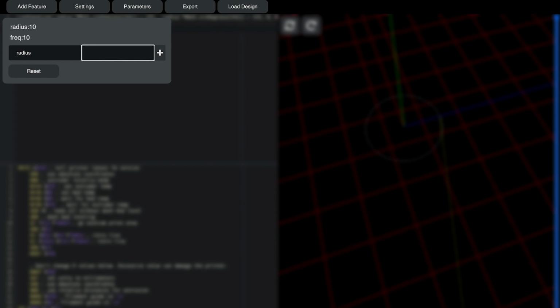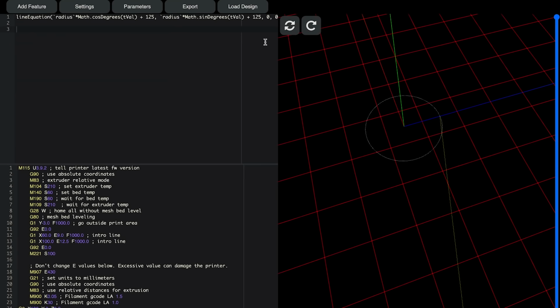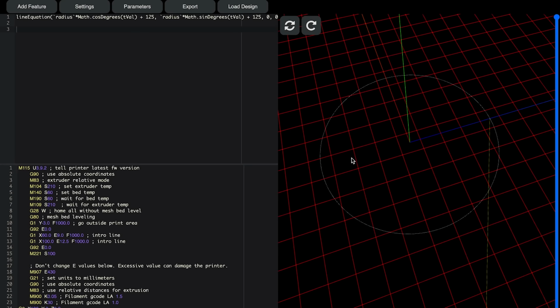Where if you want to enter it into a field that accepts expressions, it can be something like this. An expression would work, but don't reference another variable here or another parameter here. So for radius, I would increase it to 40, so things are easier to see. Let's reload. So now we have a bigger circle here. And here I would vary the radius with a sine of some value.